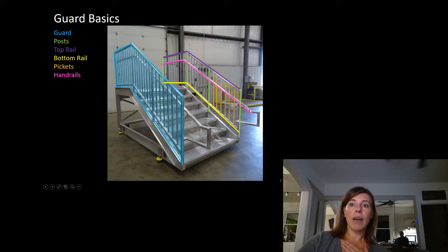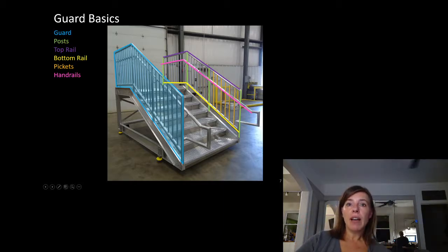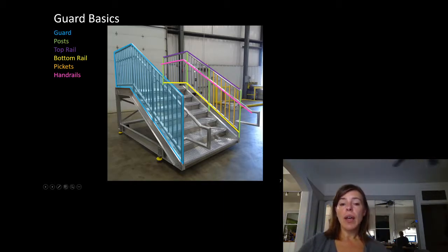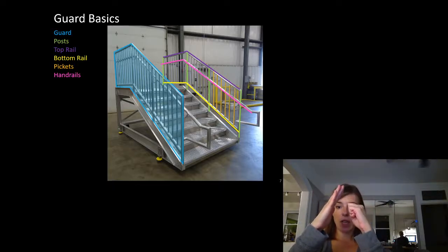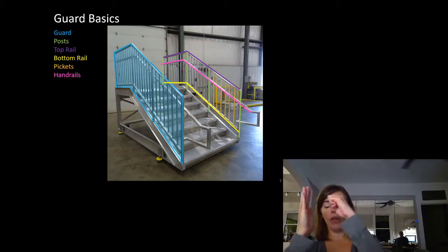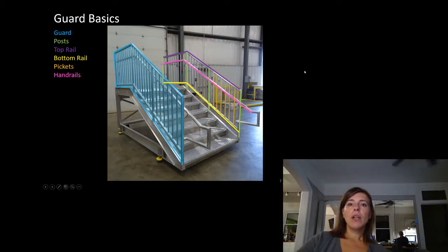So that's why you might, and if this is discrete like this is, it's pulled out, we also need to check this for its load. And then you could imagine that if this is the handrail and this is our guard and we've got that downward force, it tries to tip over our guard as well. So that's another load case that we have to look at. Well, I'll come to that in just a second.